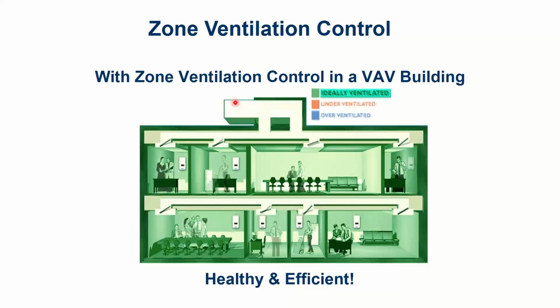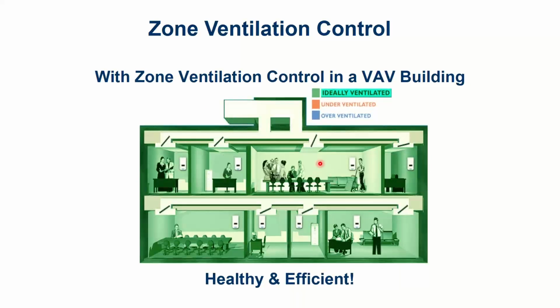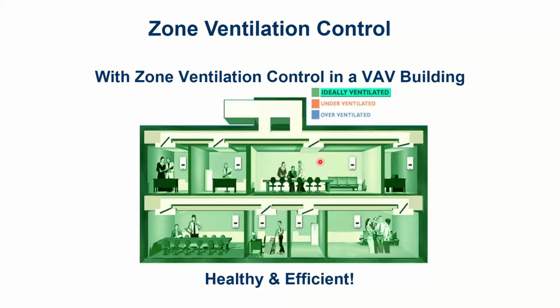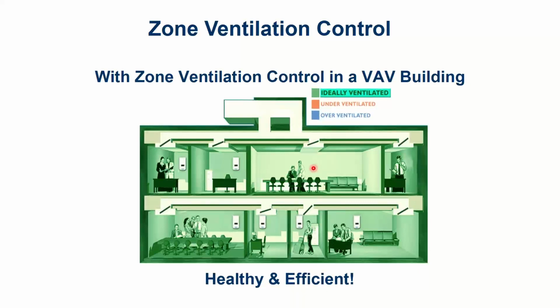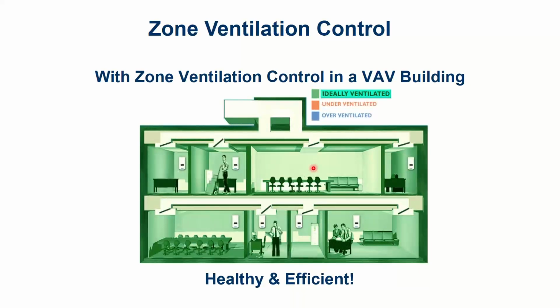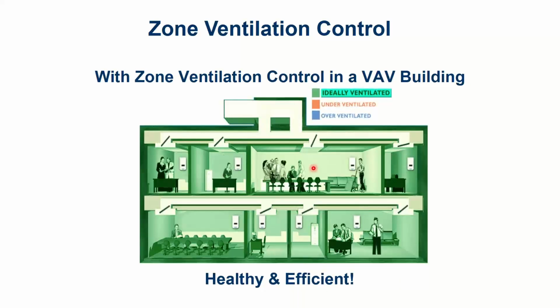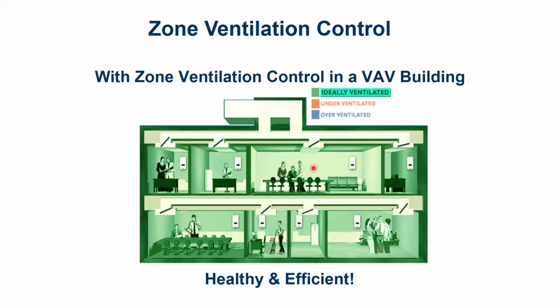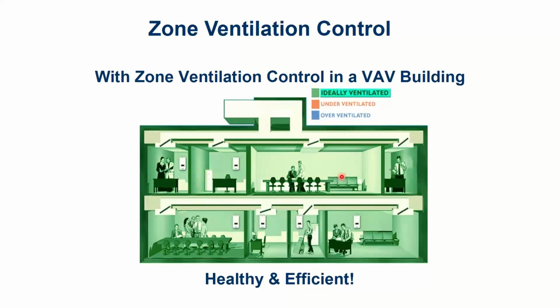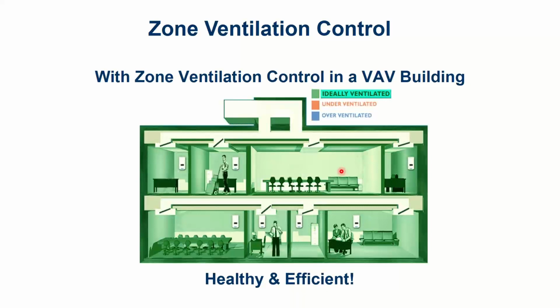And what really happens, and what I want you to think of, is as people leave those rooms, I throttle the ventilation back. If they come back into the room, I go back to what the ventilation and cooling rates would have been to begin with. So I don't have this concern with overcooling the space, because I would have always been overcooling the space if that was my problem, right? If this room is designed for 15 people, I designed everything for 15 people as if I did not have any CO2 sensors at all.